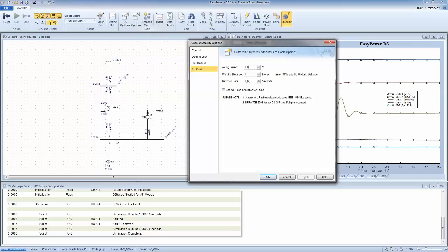If you have a fault on this bus here, and the fault current, let's say from this generator, is ongoing for a while, and before that this breaker opens because of the amount of the short circuit, the integrated method is going to look at the decay of this current and integrate it over the time, from the time that you have a fault to the time that the entire fault contribution goes to zero. It's going to account for all those changes, including the breakers that drop out, some of the motors that stop